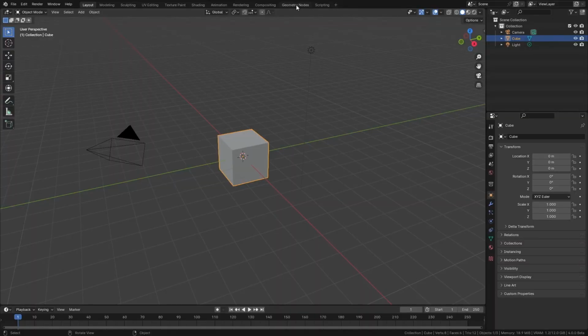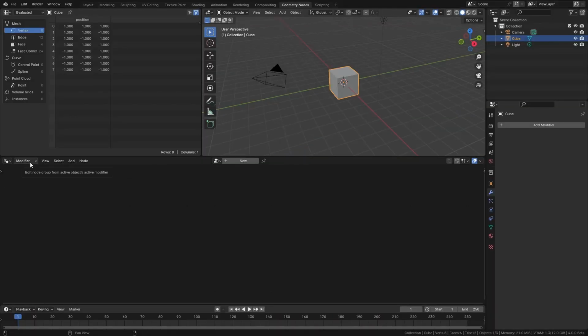Go to the Geometry Nodes tab, where on the left a new drop-down menu is located, and switch it from Modifier to Tools. Creating a new tool looks identical to your standard geometry nodes, because it basically is. But the difference here is that you can execute the node tree in a destructive way, with just one click, which previously was only done with add-ons or scripts.